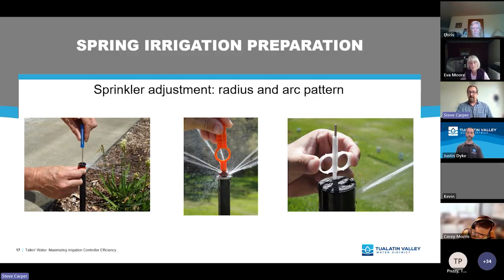But that said, optimizing these newer systems has some challenges in itself, and I'm dealing with it at my own house, trying to really get it fine-tuned. I love it and it's working well, but if the layout and system performance are not optimized and you put a weather-based controller on a system like that, you're probably going to have some challenges, because it's going to assume that the system layout and design is top-notch and really well maintained.